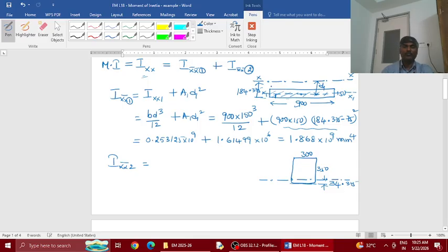34.375, because you see, you have a rectangle here. So this is your rectangle here. From here it is 184, so if you deduct this 150, it will be 34.375. So this gap is 34.375 mm. This is the overall centroidal line, the XX line, which is asked for. Now the centroid of this own figure, the rectangle, is at 350 by 2, the midpoint of this figure.